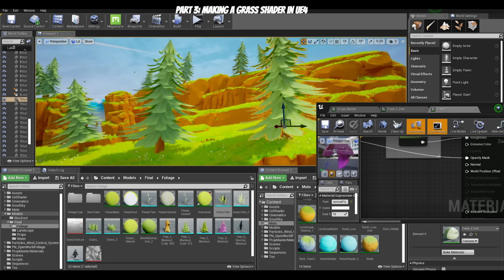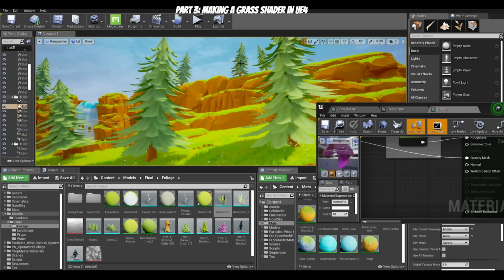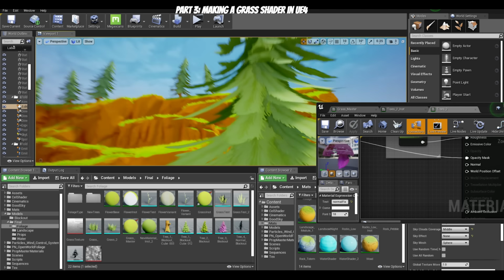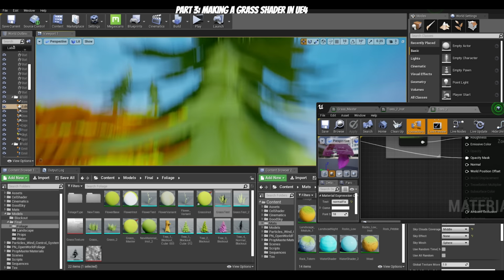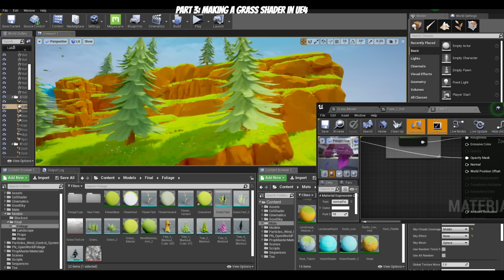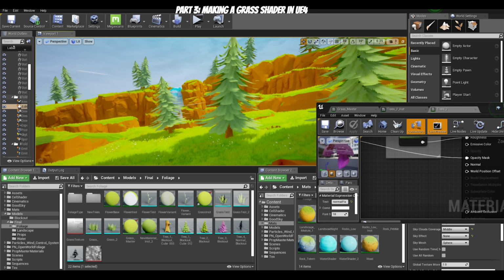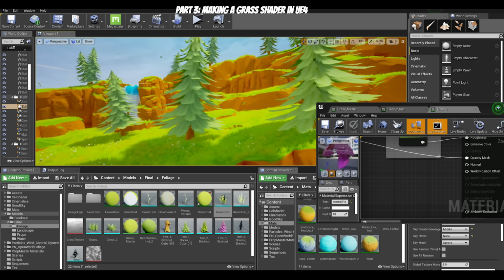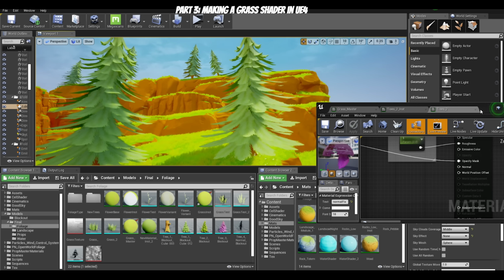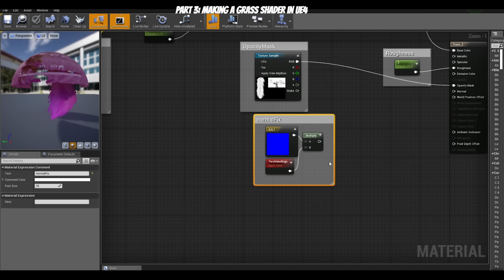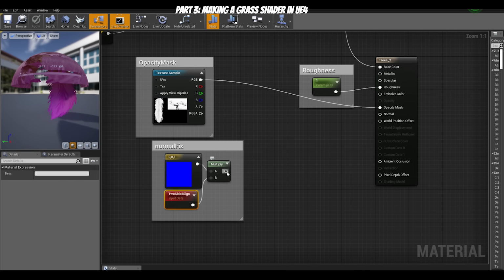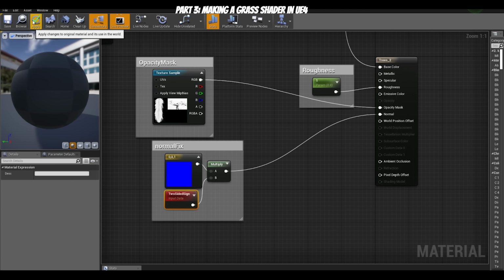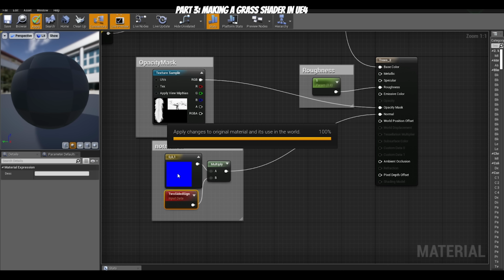All right, so I don't know if you can see this, but this is a two-sided material, right? And so these are the back faces. They are way darker than the other faces, the front-facing faces. So what this normal lighting fix does is we flip the back faces, so they receive the same lighting as the original faces.